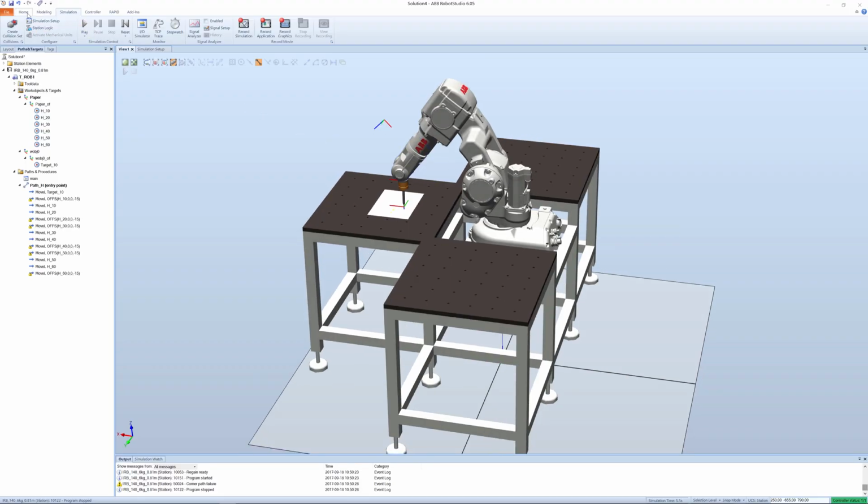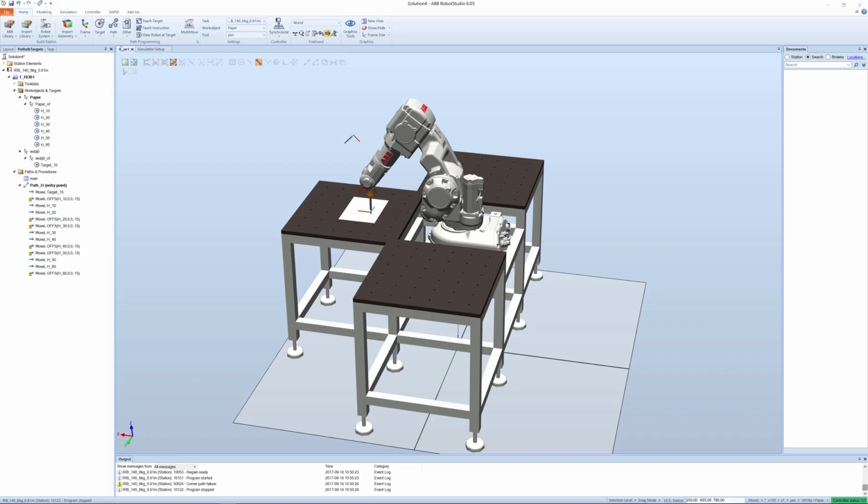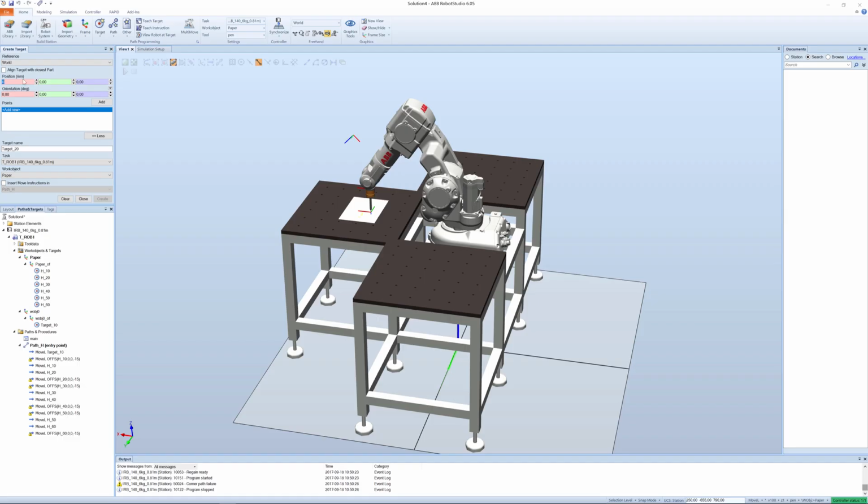Now we're ready to add another procedure, making the V character. So we change the work object here. Everything else is pretty much okay, except that we have V underscore 10 as naming. And we start now with position X is 100, upper and left of the V, and this could also be 100 and 0.